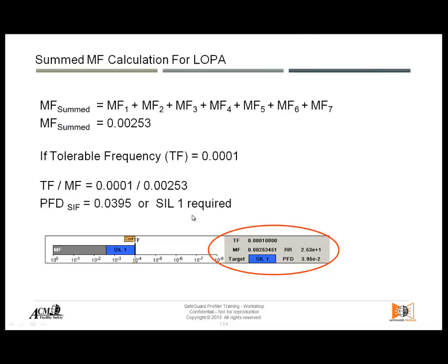Something has to be said about the equipment being used having to be inside its useful life. That's the first thing I would do, instead of trying to fix this safety instrumented function and improve it while leaving all the equipment in the field, which is not correct. The right solution in this case would be to check that all the equipment being used is still inside its useful life, and that its failure rate can be considered to be constant.